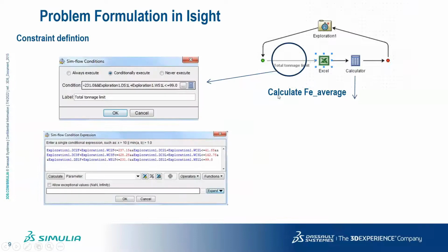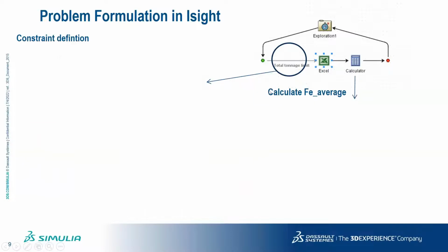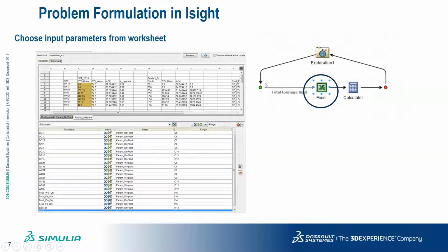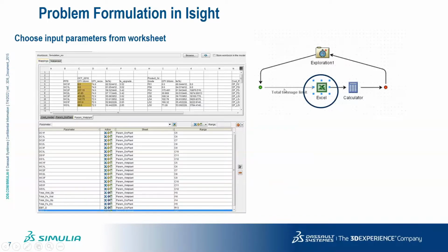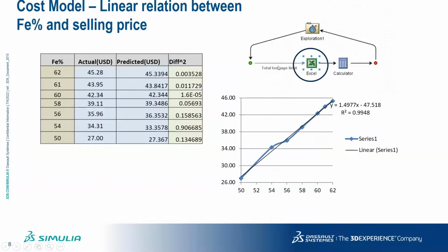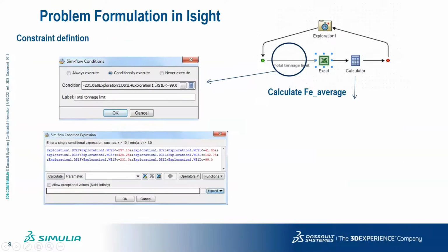And finally, we've given some conditions also. In Isight you can give a particular condition. As you see here, this particular activity will work only if this condition is satisfied. You can right click on this branch and you can always give a condition. So this was the condition that we have defined. Anything within these limits only should execute. That kind of a condition you can define.